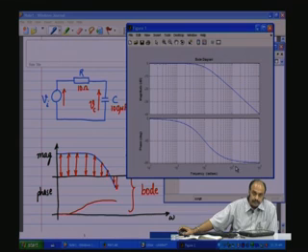This means that at very high frequencies, when it is truly behaving more like a capacitance and the resistance is swamped out, it is a capacitive load, and therefore, you have a 90 degrees phase shift. So, this is the meaning. Therefore, both the magnitude and the phase are important when you have to discuss the response of this circuit to any input waveforms in the frequency domain. This is the Bode diagram or the Bode plot.